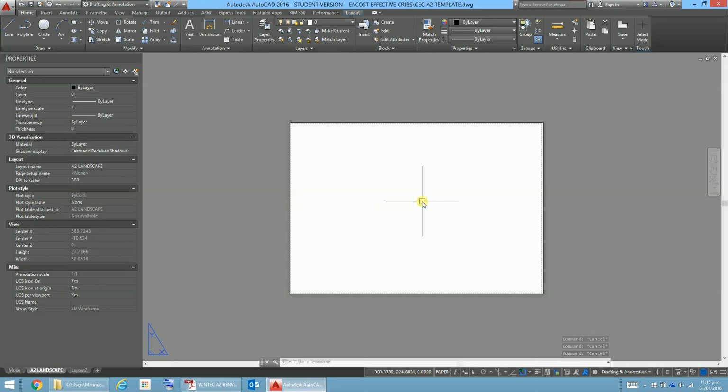There are other ways of doing it. You can use the GUI, or you can use offset here. There's the little offset command there. But typically the way I do it is just go O for offset, and you can see down here it says specify an offset distance. So I'm going to specify 15 as my offset distance, and I'm just going to click on that line and that line, that line and that line, that line and that line. And there you can see they're coming around like that.